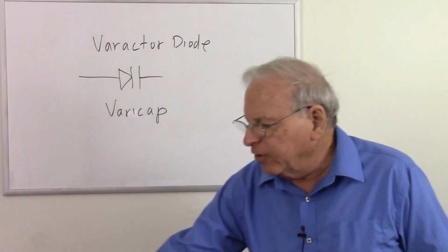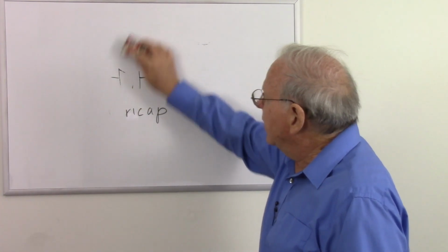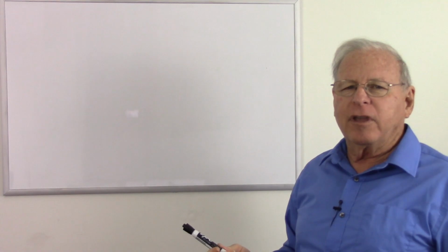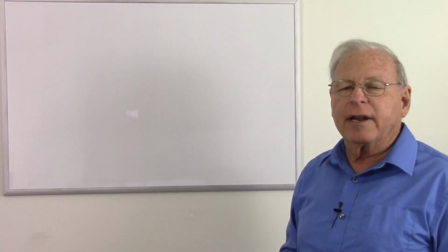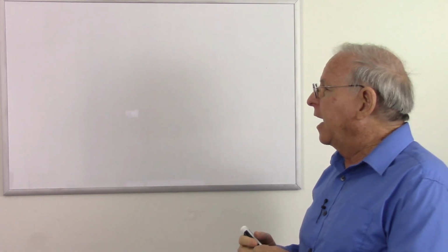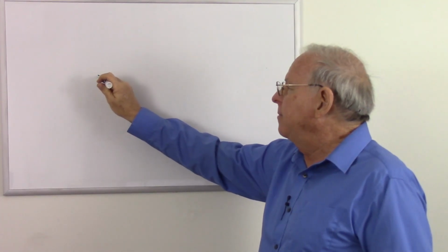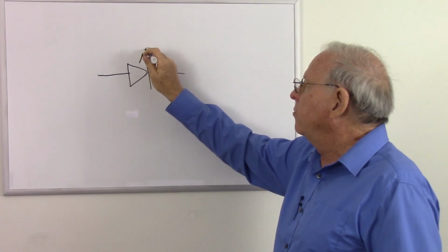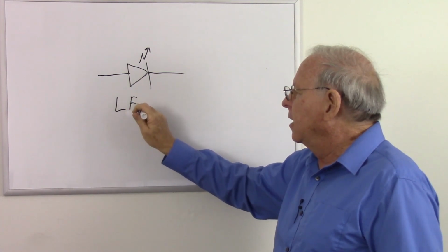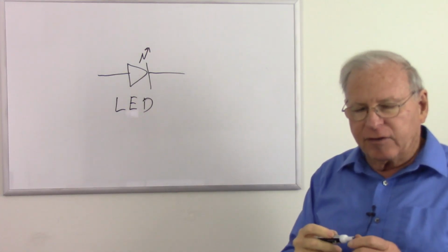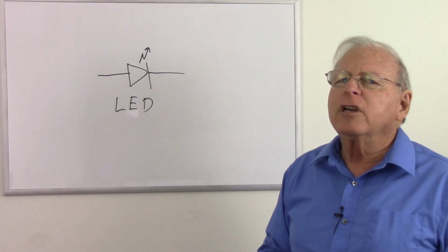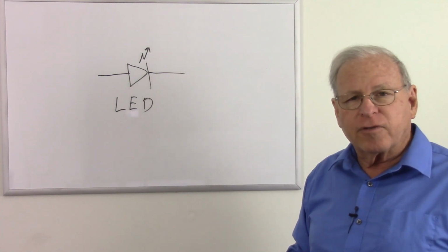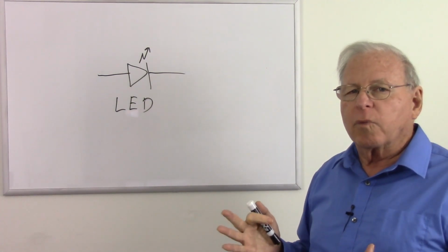Okay, another thing that happens when a diode is forward biased is it emits electromagnetic radiation in the high frequencies or very short wavelengths of infrared and visible, and maybe even ultraviolet light or close to it. The symbol for such a light-emitting diode is a standard diode symbol with a little lightning arrow, maybe 2, going from it. So that's a light-emitting diode. The color depends on the materials used. The first commercial light-emitting diodes were made of gallium, arsenic, and phosphorus. And that particular set of materials would produce red light.